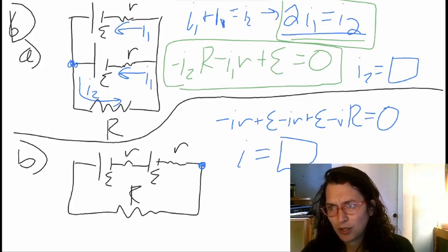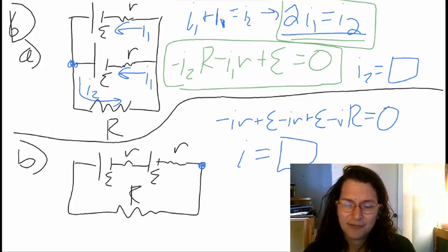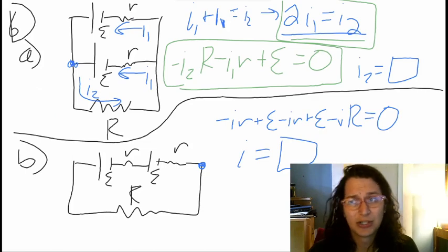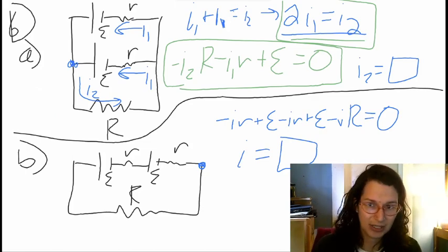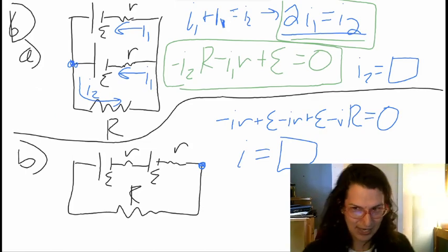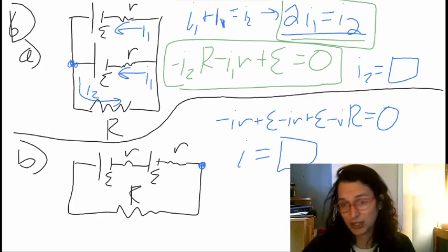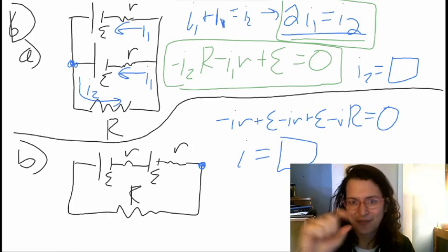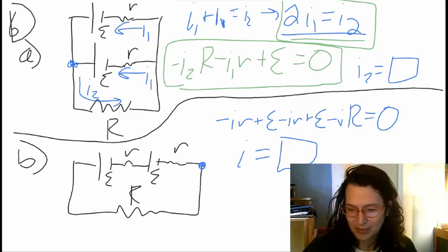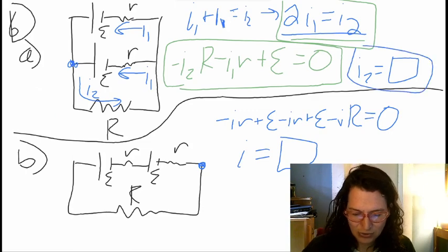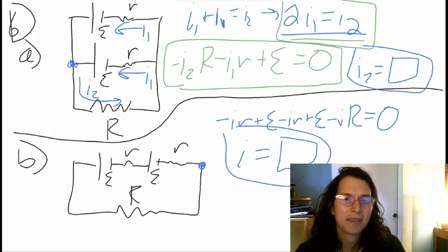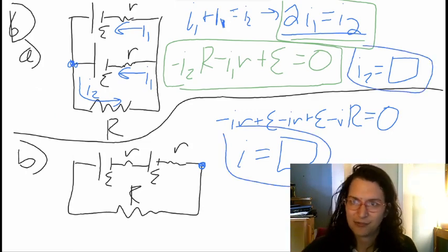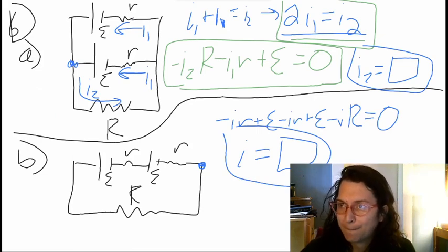And then for D, E, and F, you're going to use big R equal to little r over 2, and that'll give you a different answer for the currents in each arrangement, and ultimately which arrangement provides a greater current. However, the math in the setup is going to be the same. So my recommendation would be to generate just an expression for I2 and for little I, and then you can just plug in the different big R values for each of them.